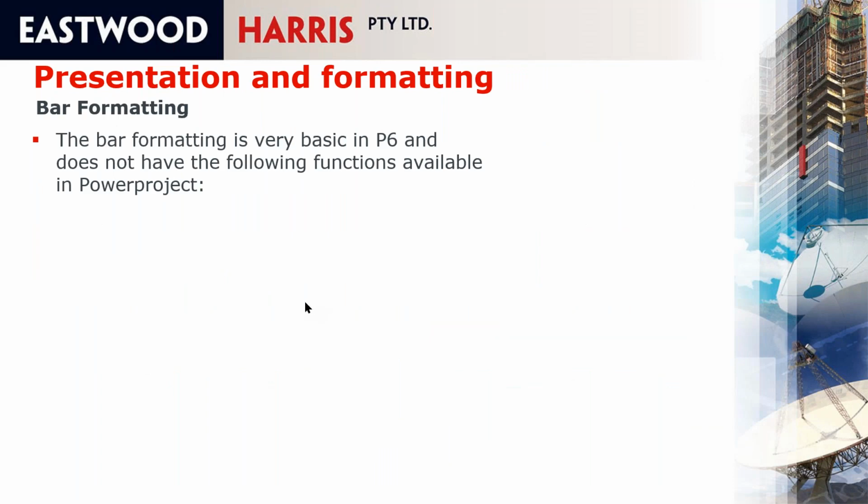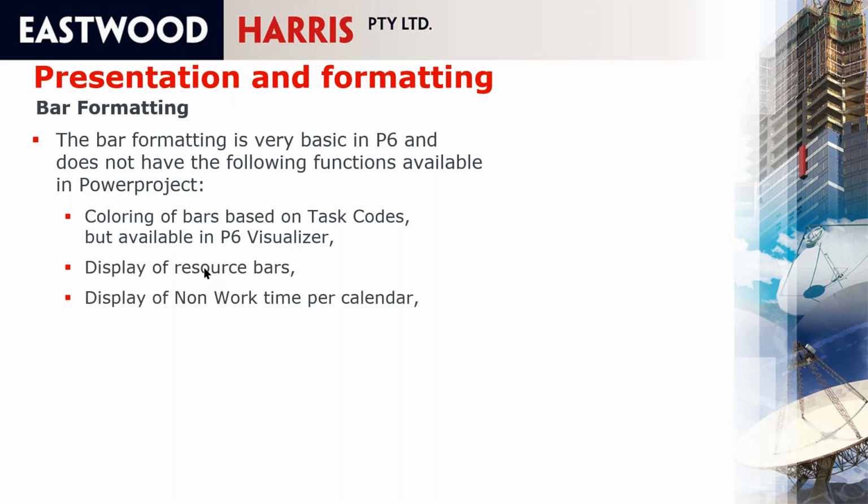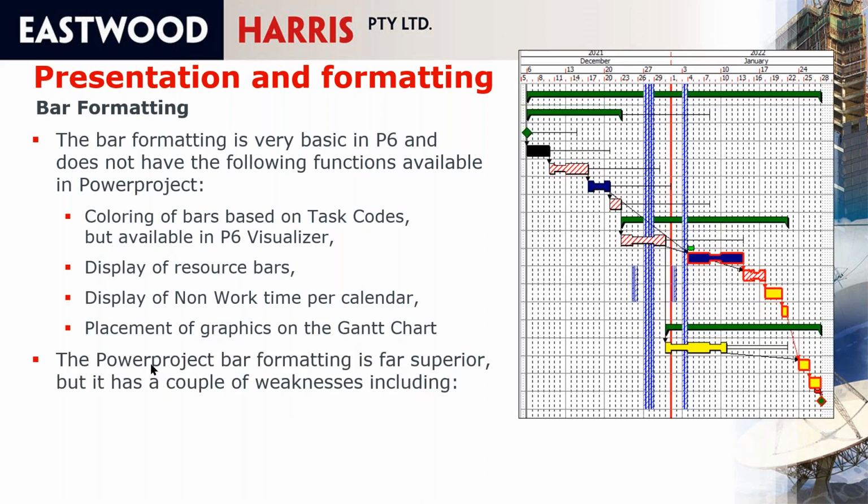Presentation and formatting: bar formatting is very basic in P6. It doesn't have the coloring of bars based on task codes, but this is available through their third-party product called Visualizer, which is a separate product they developed. It doesn't display resource bars. It doesn't display the non-work time per calendar. It doesn't allow you to place graphics on the Gantt chart, and you'll find that the Powerproject bar formatting is far superior.